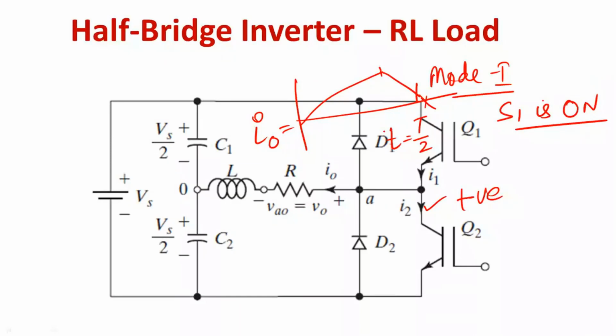This I1 value will become 0, and diode D1 will get reverse biased. Conduction continues and I2 is contributed, increasing in the reverse direction to a maximum value, then decreasing towards 0.